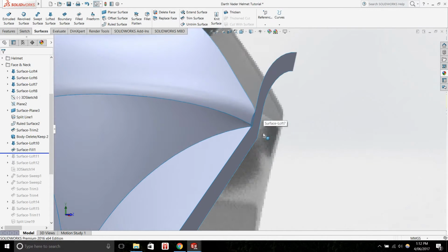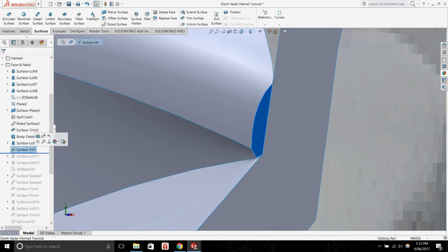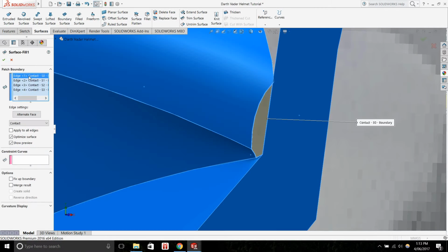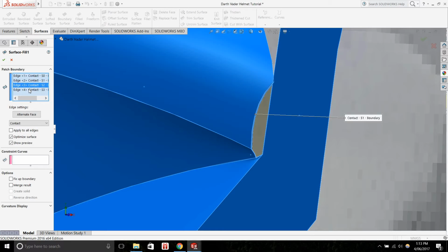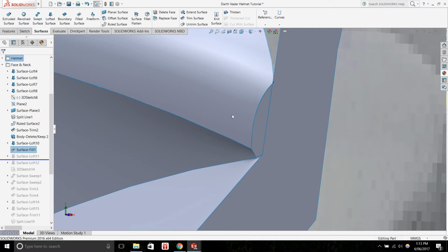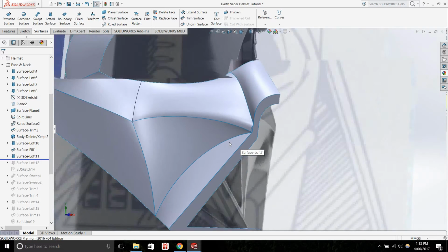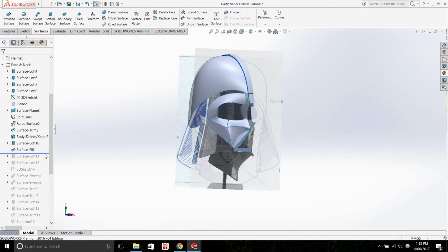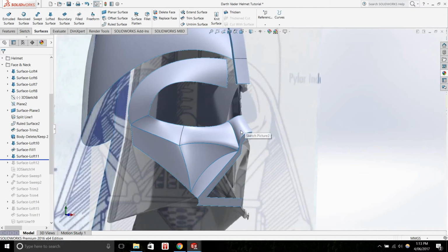Then I actually came in just there with the surface fill feature, which is another good surface tool, which is useful if you have a boundary defined by some edges. It doesn't necessarily have to be a flat plane, but just any kind of boundary, and then it just automatically fills. So I might just quickly demonstrate that. These edges were selected, and then the tool will automatically fill that area with the surface. So another surface was created on the nose section there.